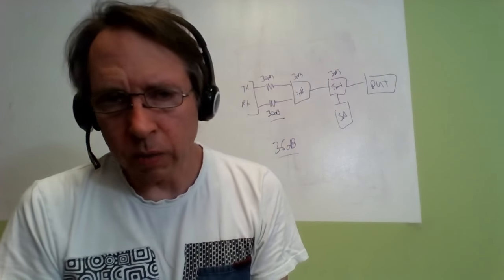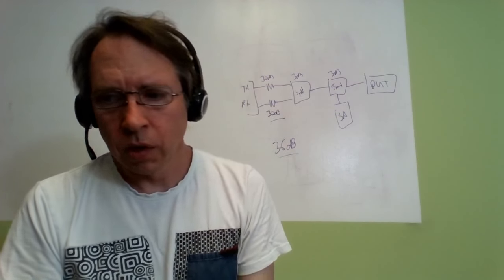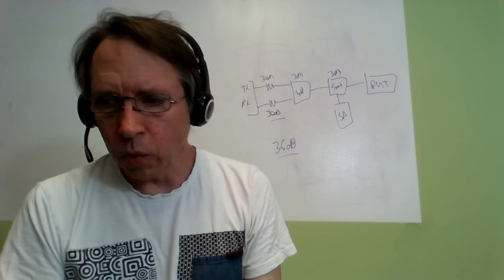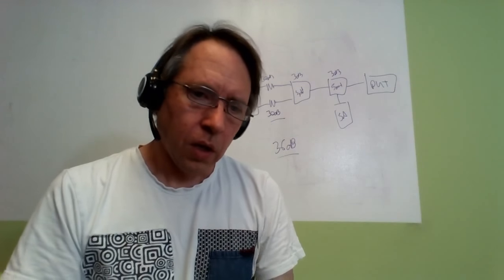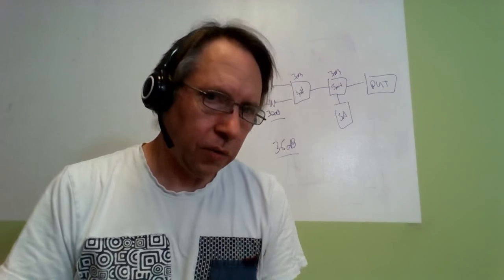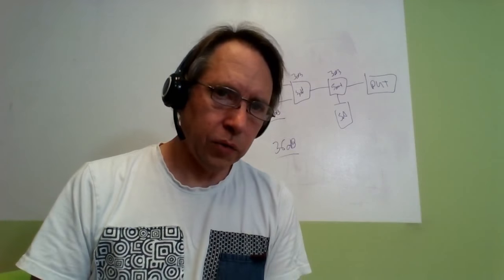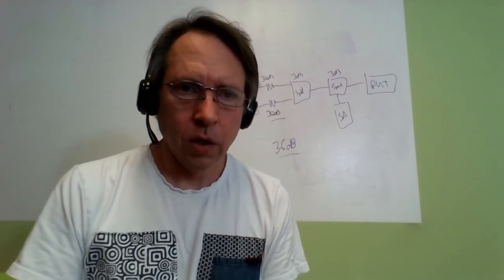And that's basically what it comes down to, is just looking at these power levels. If they differ from what you expect in your test fixture, if they differ from what you see from a known good reference device in the same test fixture, you know you have a problem. You know you're dealing with a marginal device that needs to be pulled off the line to figure out what happened to it.